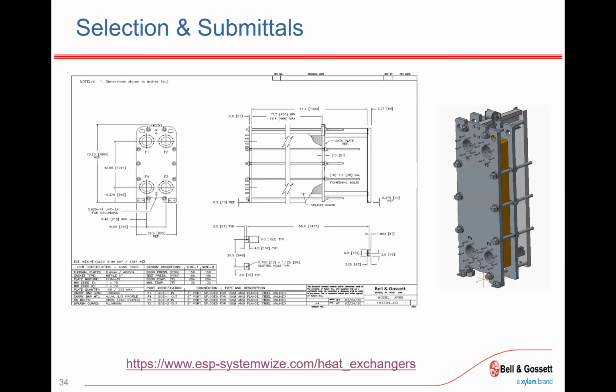but keep in mind the upfront capital cost. If you do select something at 10 psi or 23 feet of head, there's at least the potential, obviously, that your pump is going to be consuming more power. What you can do sometimes is start it at 10. I like to start it at about 15. I think that's a reasonable balance. So we're going to do 15 feet of head, and select that for both. And let's increase this flow rate to 300, 200, and then let it float, so we get a little bit larger.